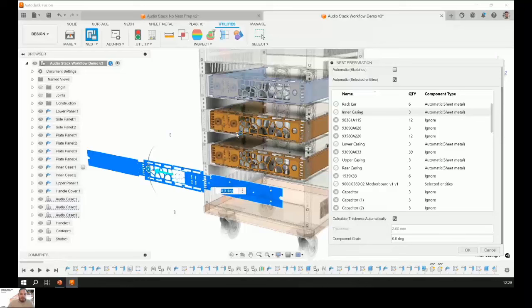Now imagine for design purposes, I might have chosen brushed aluminium or brushed steel or something. And I, of course, want that in my nesting, this component grain is going to be utilized, because I don't want varying component grain just because the nesting study will be more efficient. For design purposes, I would want the component grain to be the same.